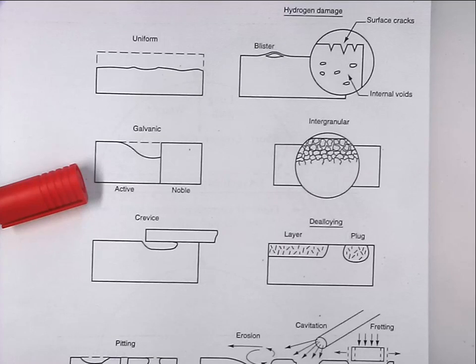So in a matter of no time at all, just a couple of years, the pipe was leaking and the pressure to the property was reduced. And that's just straightforward galvanic corrosion in groundwater. It's just buried in soil and didn't have any electrical connections to it other than the two materials, the brass and the steel, being connected together.